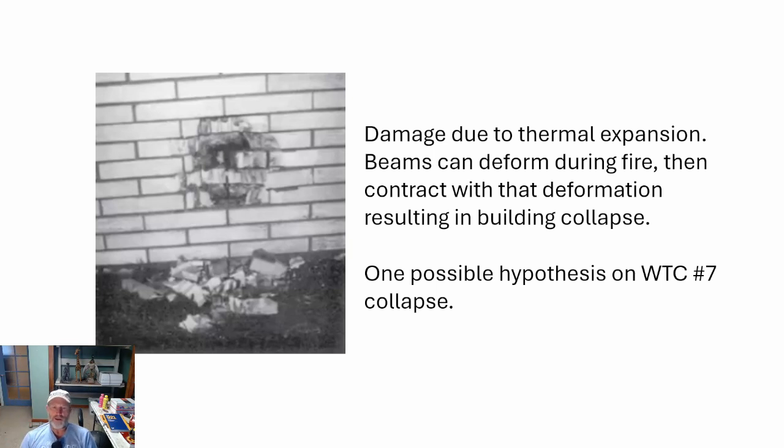So with the World Trade Center, it was kind of interesting. You had a building, it was 110 stories tall, WTC1 and WTC2. Each floor was an acre. It was about 207 feet wide, I believe was what the number was. And what was interesting about WTC1 and WTC2 is that you had a center column of concrete that handled your elevators, your HVAC shafts, your stairways.